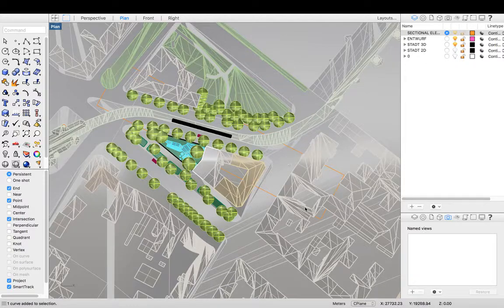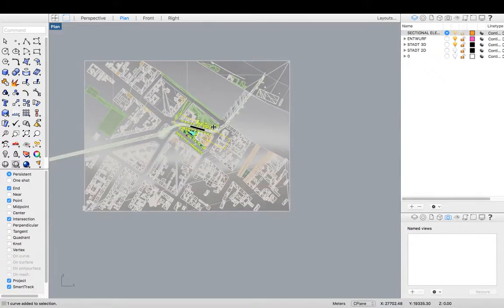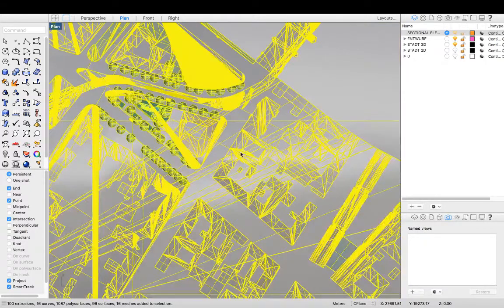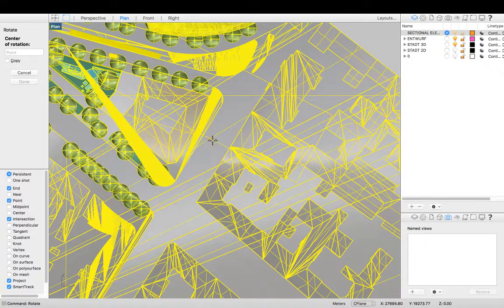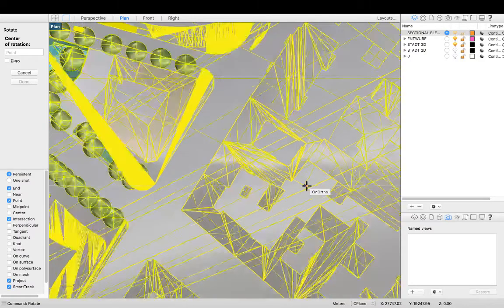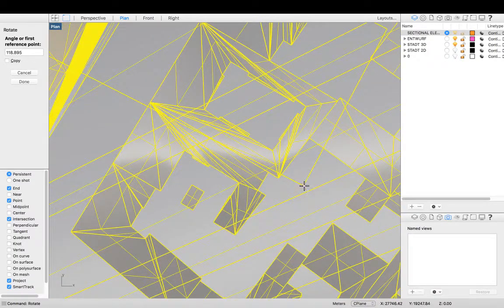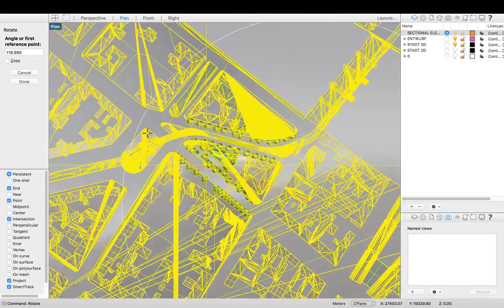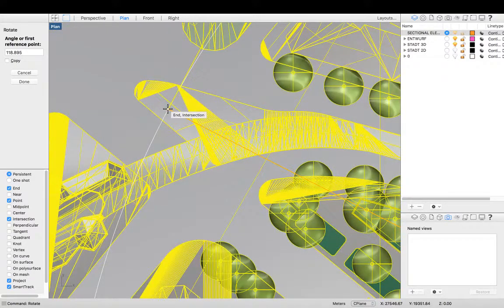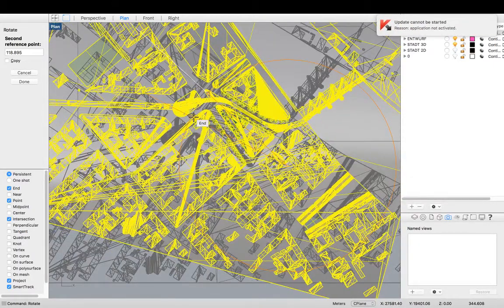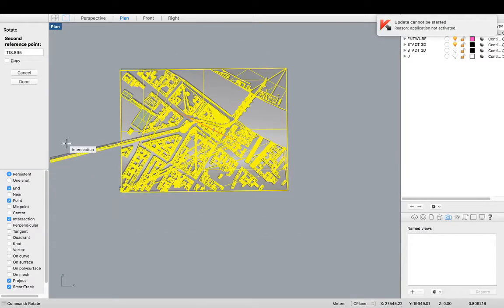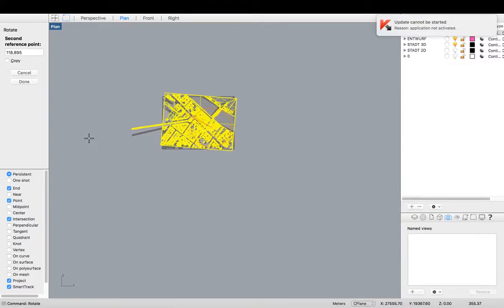First thing we have to do is rotate this box to be horizontal and flat in our plan view. So we're going to select everything using Command A, and we're going to rotate by selecting one end. Sometimes it can be a bit tricky to see where your original section line is when everything's yellow, but I can see that it's here, and it's here. There we go. And I have orthographic selected, which means it snaps to horizontal straight without me having to press any further function.